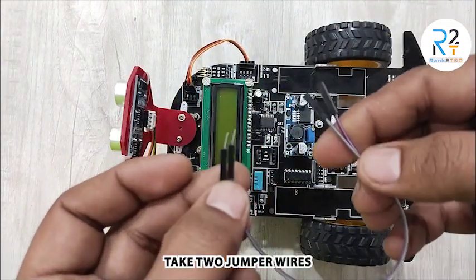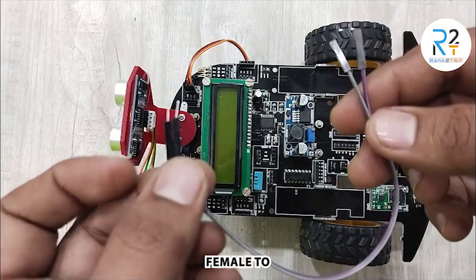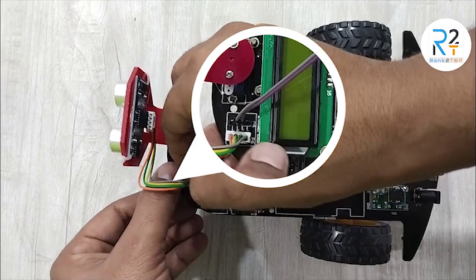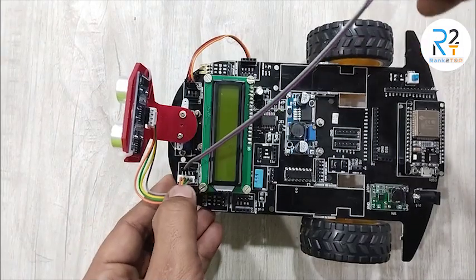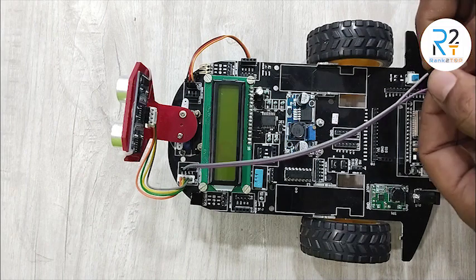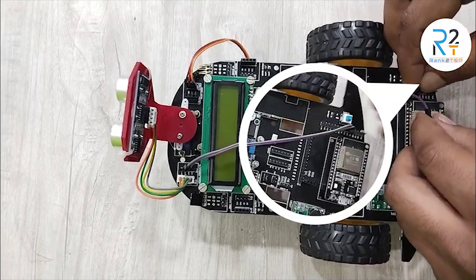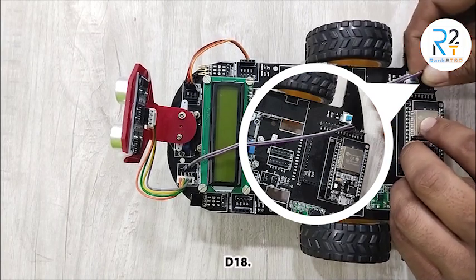First, take 2 female to male jumper wires to connect the echo and trigger pins with the microcontroller. The gray wire is our trigger pin. Trigger pin connects with D5 and echo pin with D18.